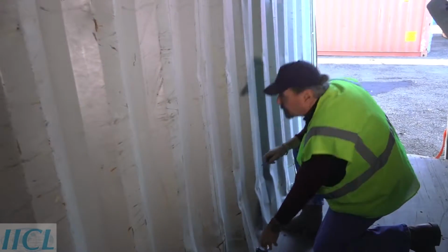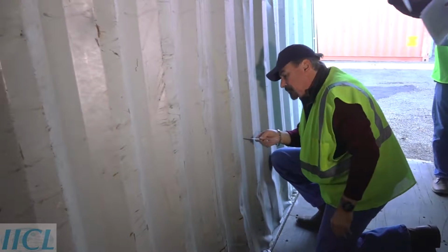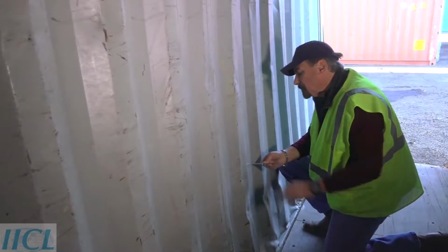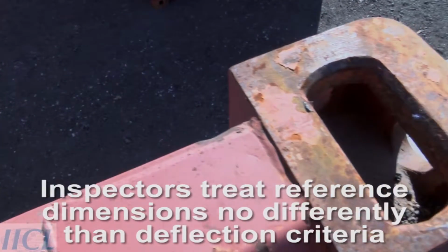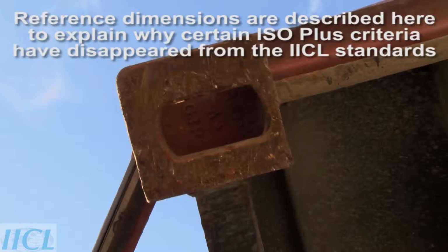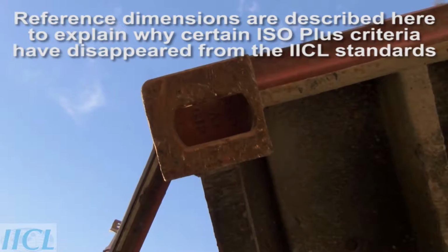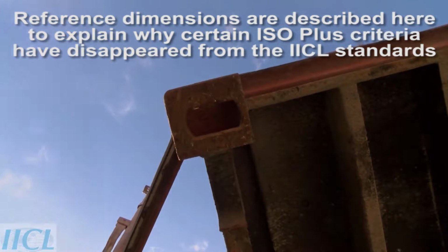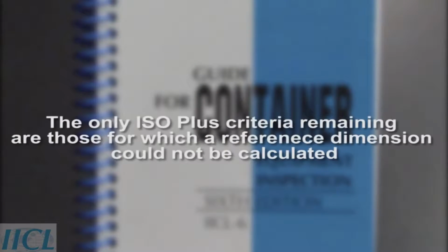The side panel outward damage measurement example shown later in this video is an example of the application of a reference dimension. Inspectors treat reference dimensions no differently than deflection criteria. Reference dimensions are described here to explain why certain ISO plus criteria have disappeared from the IICL standards. The only ISO plus criteria remaining are those for which a reference dimension could not be calculated.